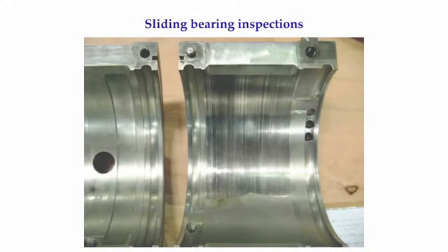Here is heavy wear on a bearing. Notice how the wear marks are not at the bottom of the bearing. In this case, the shaft was probably forced in a sideways direction, potentially from a running shaft misalignment condition.